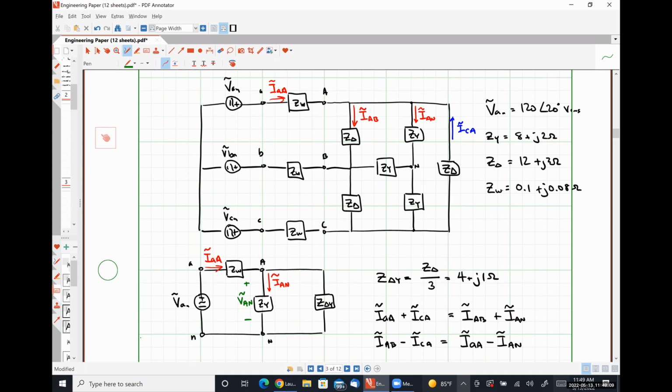Same exact thing for this, the phase currents. We could have absolutely done it as AC leaving, but then it would, to me, take extra effort to figure out what the actual phase angle is supposed to be relative to the A phase of the system. So yeah, bookkeeping wise, this makes it easier for my brain to interpret. So that's why I'm going to do it. All right. So we have the math in place to figure out how we're going to get effectively everything. Now let's go through it.